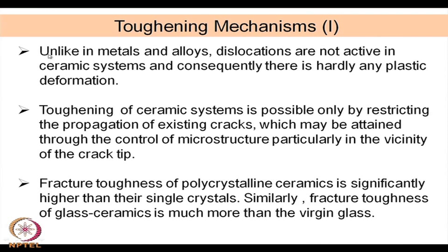So, the fracture toughness of polycrystalline ceramics is significantly higher than that of single crystals. Similarly, the fracture toughness of glass ceramics is much more than that of virgin glass. This is a consequence of how to restrict the movement or propagation of the cracks.